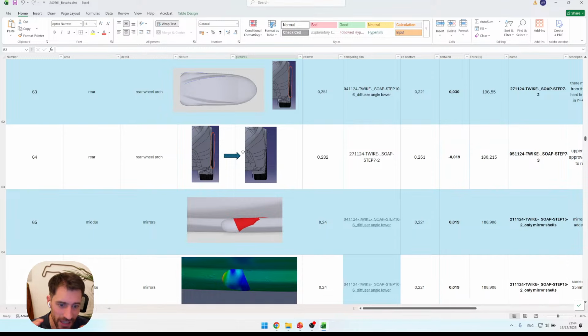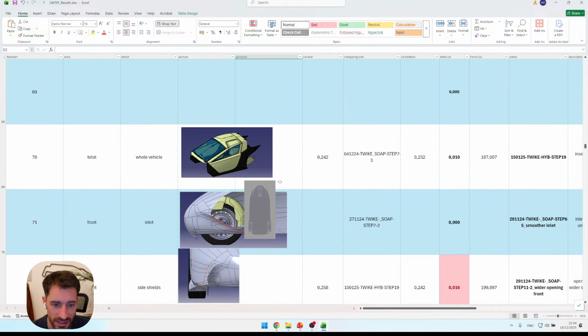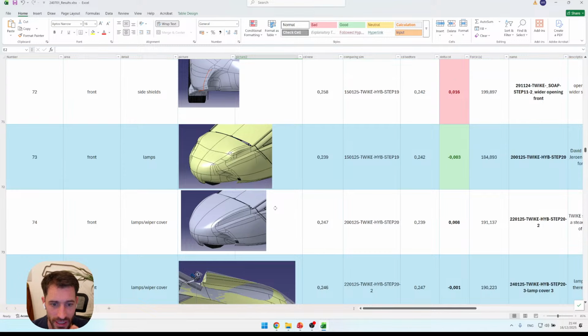All of these isolated areas were coming together into one nicely morphed, organic, complete picture of the car, which is really nice to see. We started optimizing the nose together with the deflector, together with the side channels, together with this flow, nicely feeding air underneath the car, together with the side flanks on the car. So it's a very organic looking shape, which goes far beyond these isolated 2D optimizations that you sometimes see on cars.